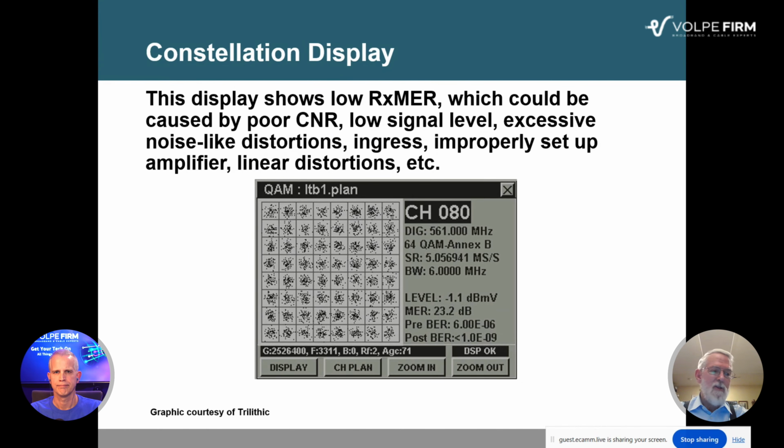And this is a notorious one that makes me gnash my teeth and pull my hair out: people will get amplifiers from the vendors who have configured these things with certain values of pre-stage, interstage padding and equalization, if equalization is used. That's done to come up with an optimum trade-off between distortion and noise performance.